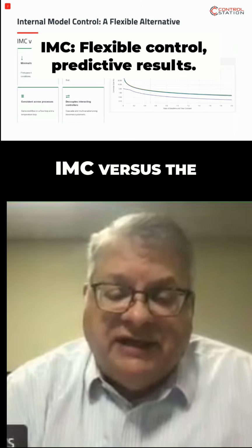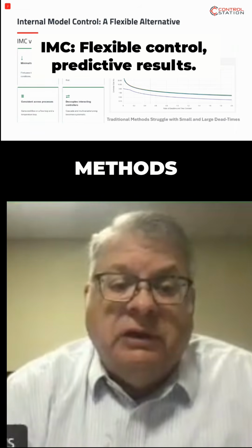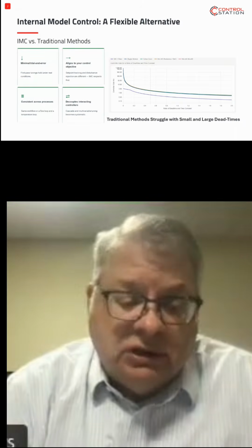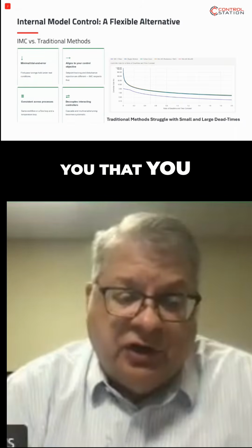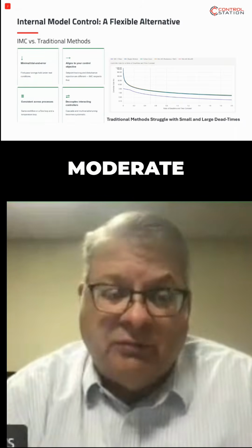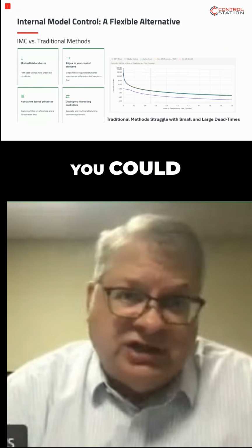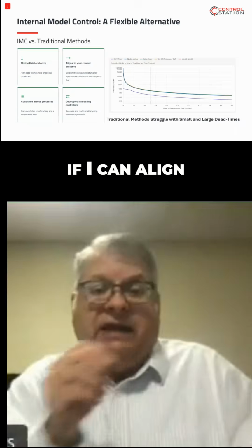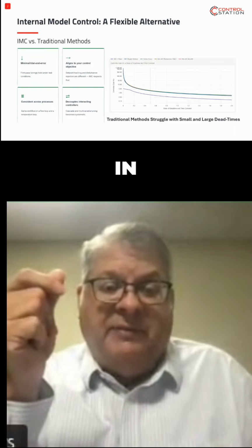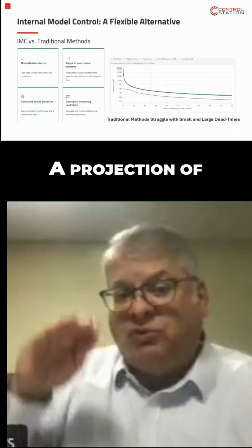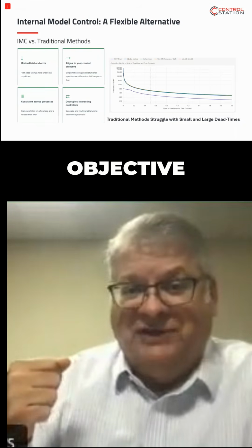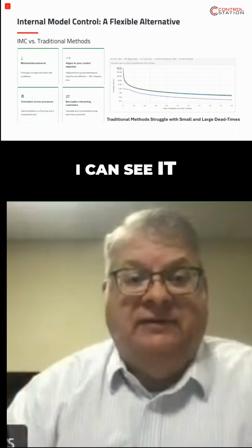If we look at the IMC versus those traditional methods, really this internal model control is very flexible. I was sharing with you that you could go between conservative, moderate, moderately aggressive, aggressive. You could select all that within the process. The nice thing about that is if I can align that slider bar in a piece of software that quick and get a projection of what it's going to produce, I already know if it's going to meet my control objective. I can see it, right?